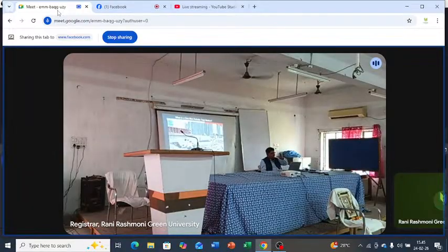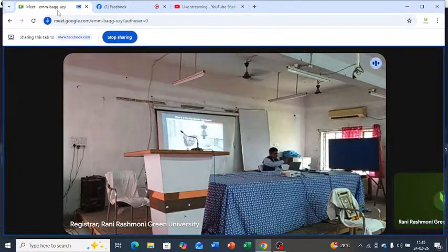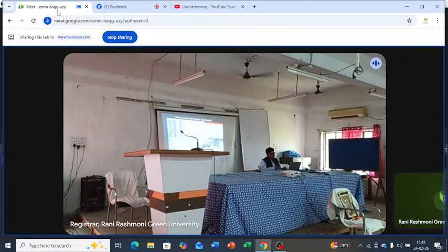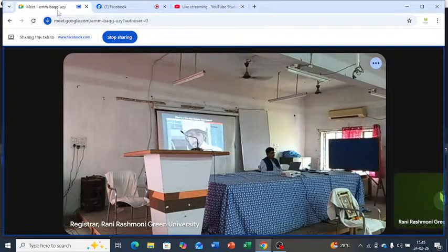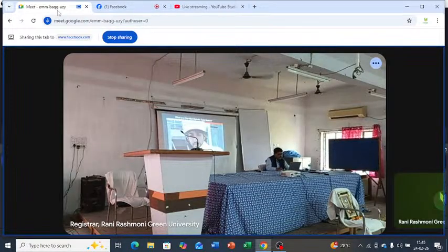And this is automatic, or it can move in the horizontal and vertical direction. It can find the prism also. Even if the prism is moving, it can track. First you take a distance measurement to the prism and then lock it, then the instrument will follow you. So this is called a one-man robotic photo station.